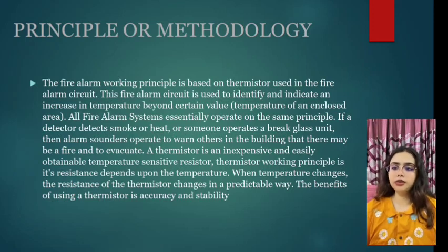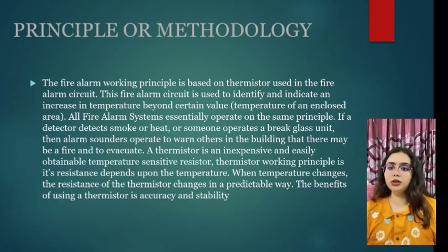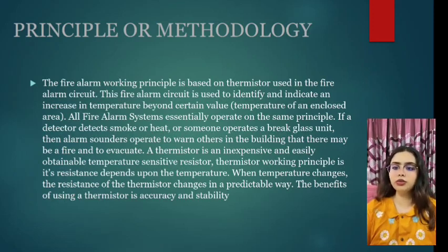All fire alarm systems essentially operate on the same principle. If a detector detects smoke or heat, or someone operates a break glass unit, then alarm sounders operate to warn others in the building that there may be a fire and to evacuate.